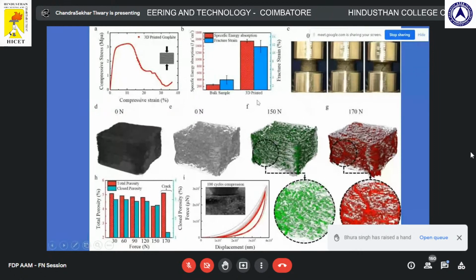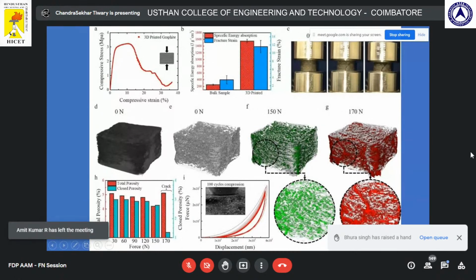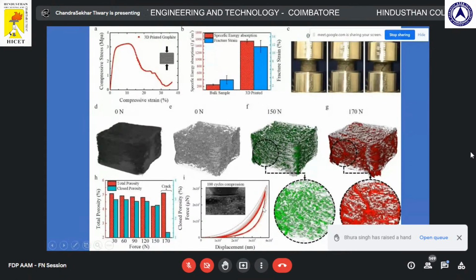All of these are explained. One interesting observation: graphite is brittle, but if you take graphene and print the same solid block, it has a huge ductility. The specific reasons are explained in the paper. We do a detailed X-ray scan and try to understand the crack propagation, deformation mechanism, and so on. But interestingly, this ductility is not just once, right? You can keep on applying load under certain conditions and it can replicate. All these details are in the paper. I'm not going to go into detail.